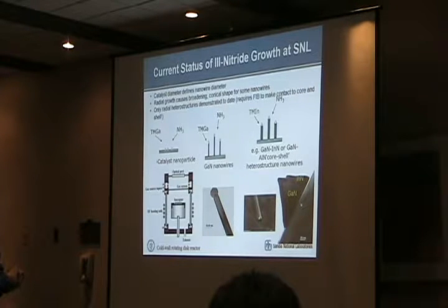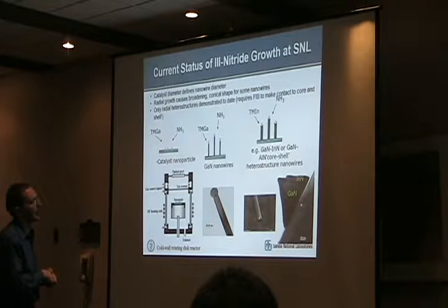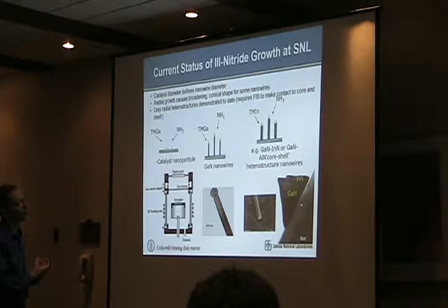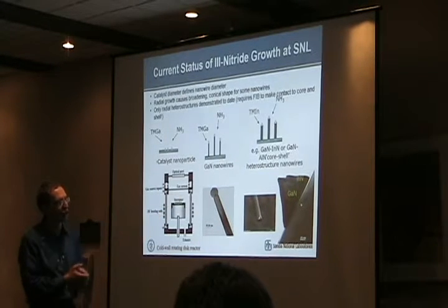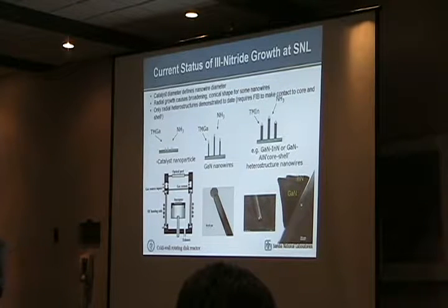The trimethyl gallium and ammonia, in our case, which is MOCVD growth, are brought in a CVD reactor, and they saturate the catalyst metal, and a single crystal nanowire precipitates. You can see the catalyst particle. I'll show you some three-dimensional images that are reconstructed from scanning transmission electron microscopy tomography, so you'll have a better view of what these nanowires look like.